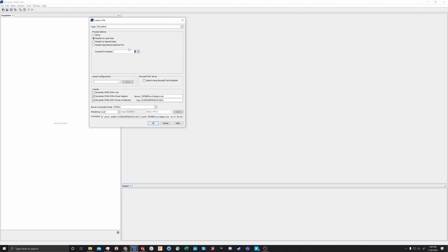For the setup process, I find that runs faster with the volume mesh that we're going to create. That's the main multi-threaded process that we have. And then later on the line, I'll up that based on the number of threads. I usually run on 28 to 30 threads on this computer. I've got 16 physical cores and 32 threads.